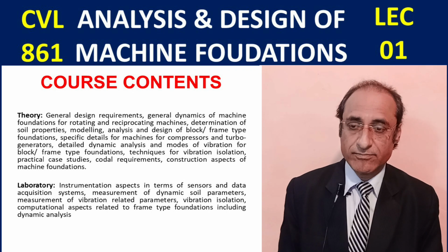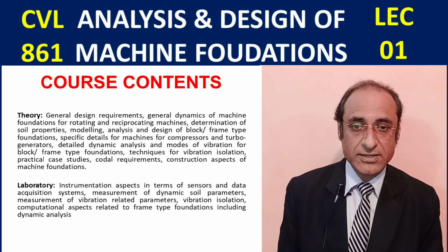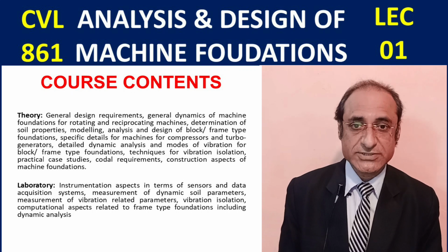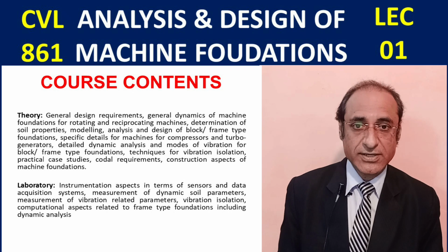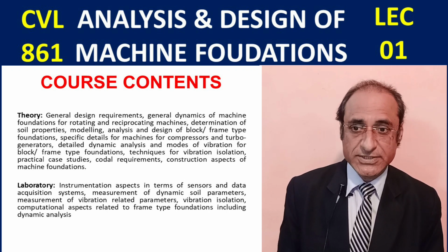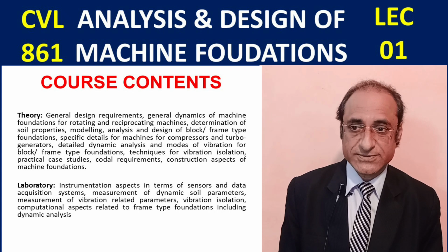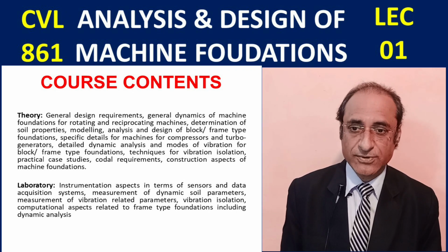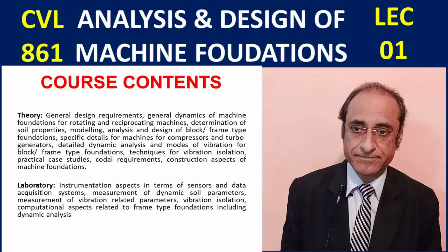Now here are the main course contents. We'll cover general design requirements, general fundamentals of dynamics of machine foundations, both rotating and reciprocating type machines, determination of the soil properties, modeling, analysis and design of block and frame type foundations, specific details for machines of compressors and turbo generators, detailed dynamic analysis and modes of vibrations for block and frame type foundations. We'll also discuss the practical techniques for vibration isolation along with practical case studies.